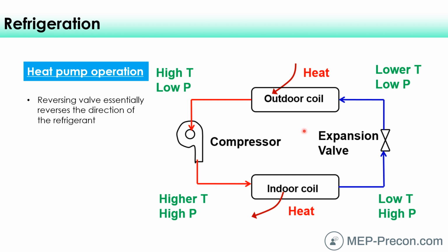Not very efficient that way, because straight electric heat used in that way uses a lot of energy, and electricity is pretty expensive. It's more expensive than gas for the same amount of BTUs. But the refrigeration cycle can be really efficient if the outdoor ambient temperature is a little bit warmer that way.